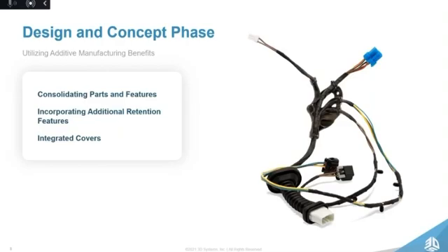It also means that not only can the part be designed for conformal geometry for fitment and fixing, but also for the ability to assemble with guides, retention features and closures. Importantly, these features don't need assembly prior to installation, but can be included in one single part. And when I say features, I mean features such as clips, covers, closures, channels for zip ties, and the like.